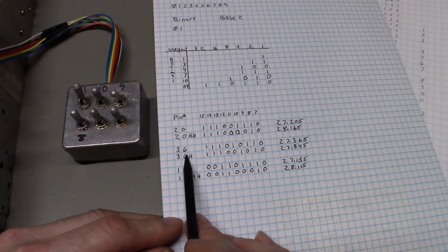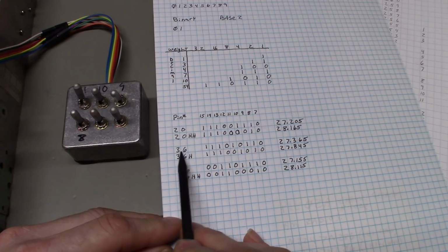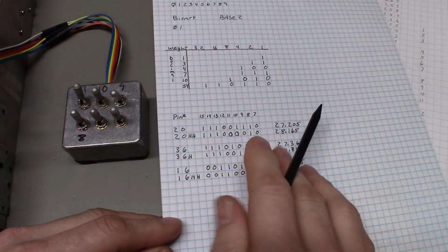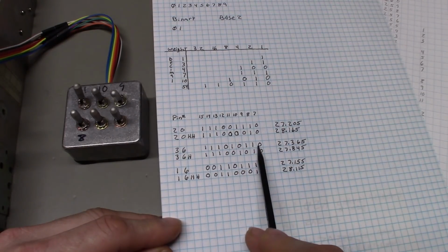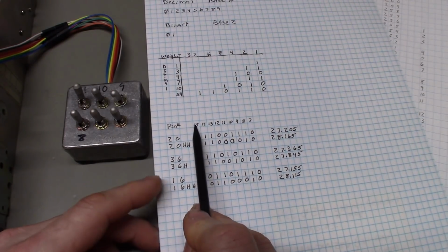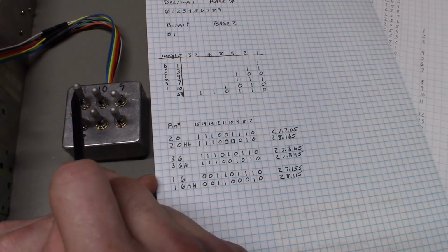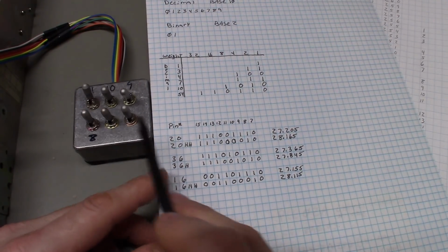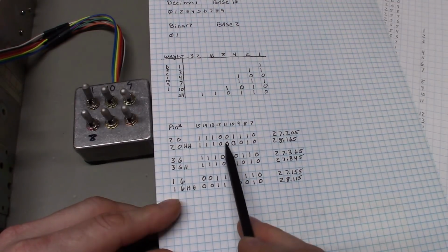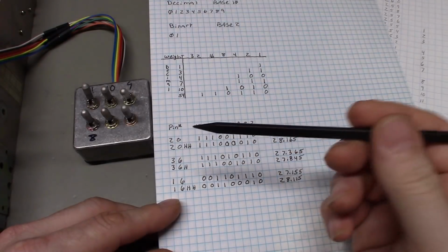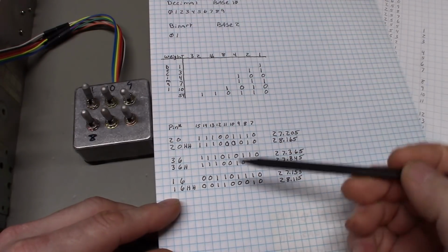So I've written down the decimal, or the channel number. I've written out the binary code. Remember, this is backwards because we're going from least significant to most significant, but I have the pin numbers up here, so from pin 15 to pin 7, and then I have, remember, toggle switches here that are actually attached to, what, 11, 10, 9, and 8. So this one, this one, this one, and this one have toggle switches that we can change the states from high to low, back and forth.